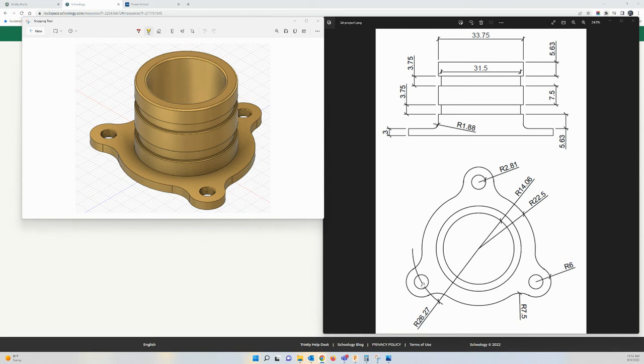We have this other measurement. This is to the center point of these holes out here, where these holes are what we will use to connect the coupler to the other object. And the example I used earlier would be the pressure washer. We know that the radius to the center point of those holes is 26.27 millimeters. Multiply that by 2. That gives us a diameter of 52.54 millimeters. You can check me on a calculator.